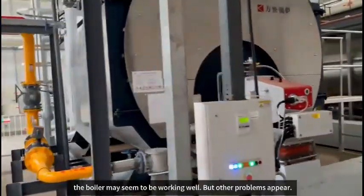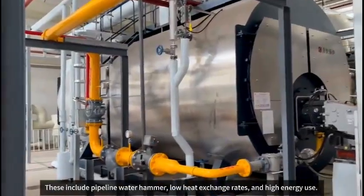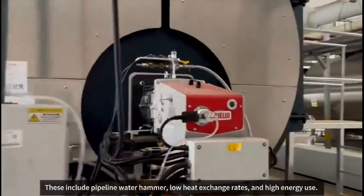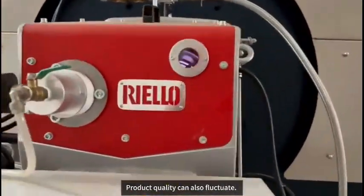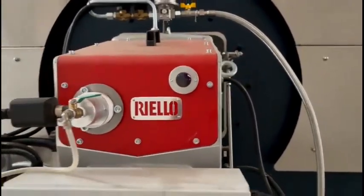Because of this, the boiler may seem to be working well, but other problems appear. These include pipeline water hammer, low heat exchange rates, and high energy use. Product quality can also fluctuate. The root cause is often the same: poor steam quality.